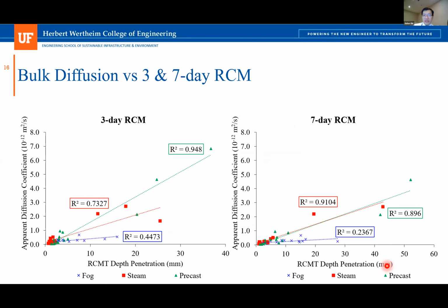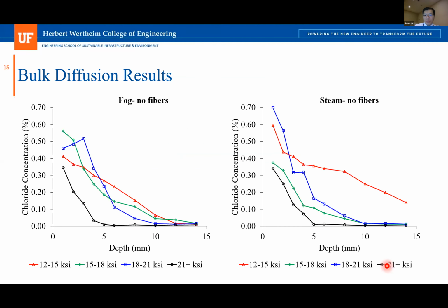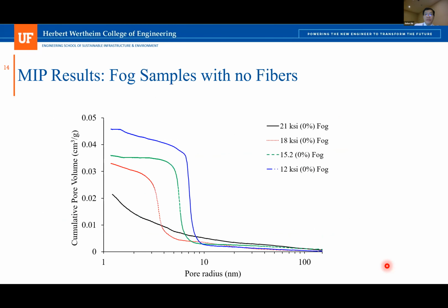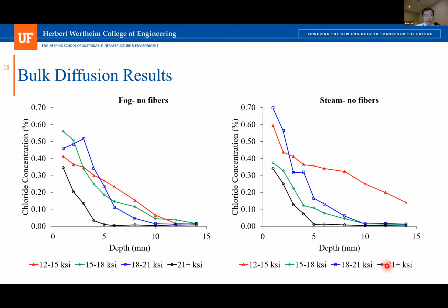So I was just curious about the steam curing, because from typical steam curing of normal strength concrete, your temperature was probably above 75 or 80 degrees Celsius. Correct, it was 90 actually. So in that case, based on existing literature, there may be a risk in the long run in terms of delayed ettringite formation, or DEF. Have you considered that?